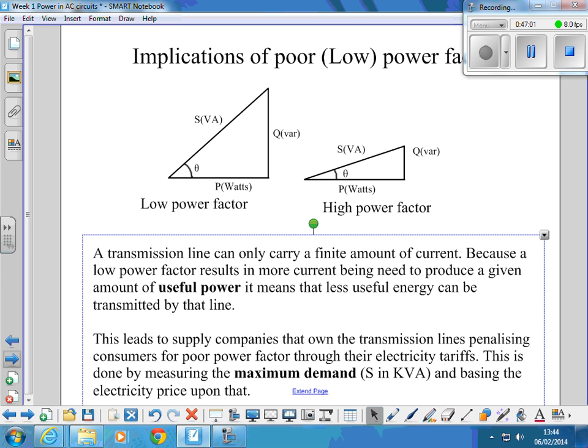You know, the types of things where it pushes a maximum marker up beyond where it was before, so when it falls back, the marker stays. Probably electronic now, but they'd have a meter that indicated what your maximum demand was in that month. I think you used to take a reading of demand every so often and then record what the highest was. And they'll then make a monthly charge based on that highest demand.